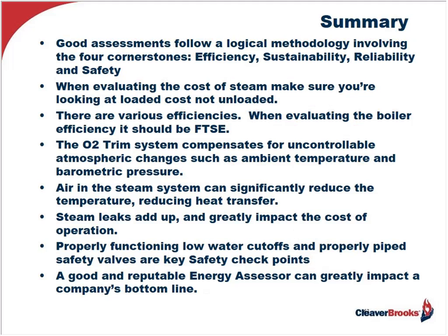So here are your takeaways today. Good assessments follow a logical methodology involving the four cornerstones. When evaluating the cost of steam, make sure you're looking at loaded cost, not the unloaded. Make sure you've got all the costs included in the cost of steam. There are various efficiencies. When evaluating the boiler efficiency, it should be the fuel to steam efficiency that you use.